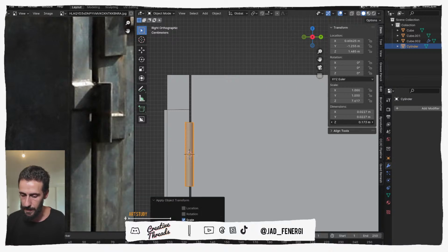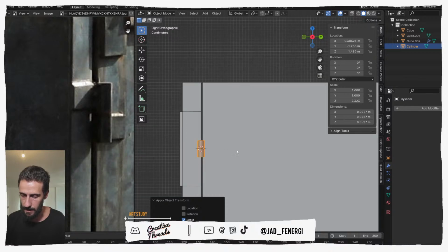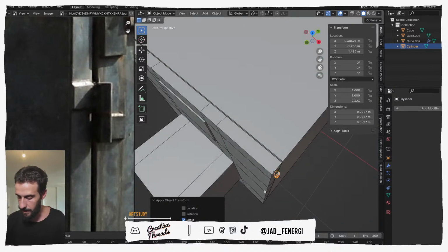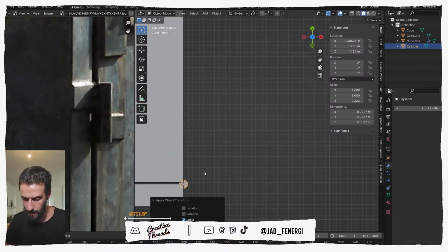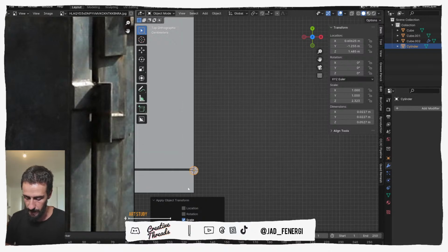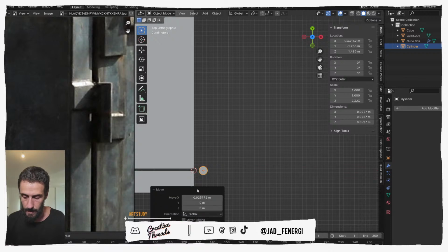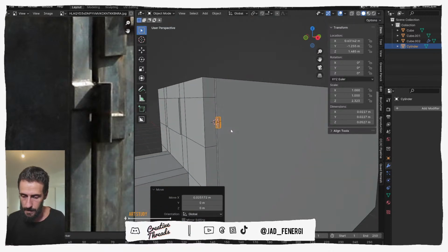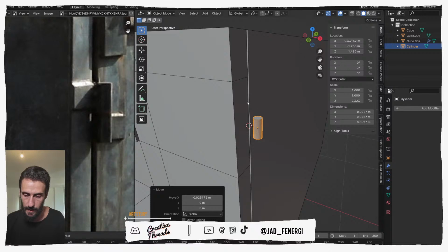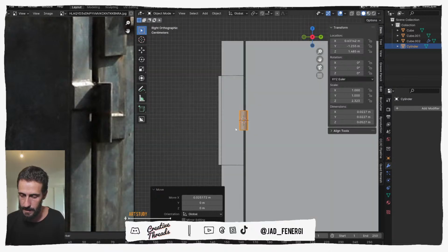We can make it bigger on the Z axis in terms of dimension, not scale. But again, Blender usually prefers higher scale objects, so it's a bit hard to work with when you're working with centimeters. Right, so we move this on the X by pressing G X, and you move it outwards like this. So what we want to do is also create this box, the same thing.